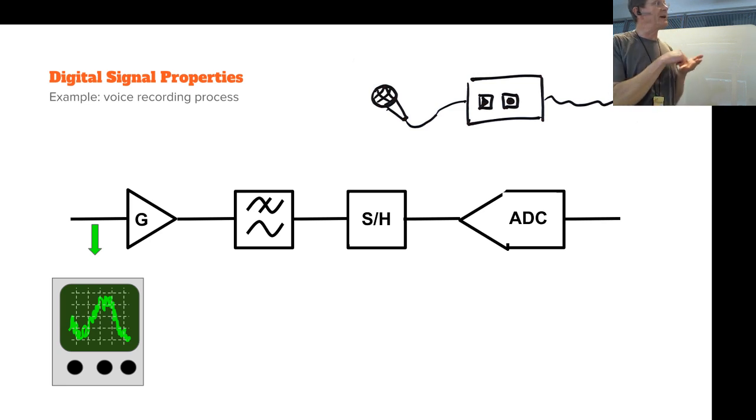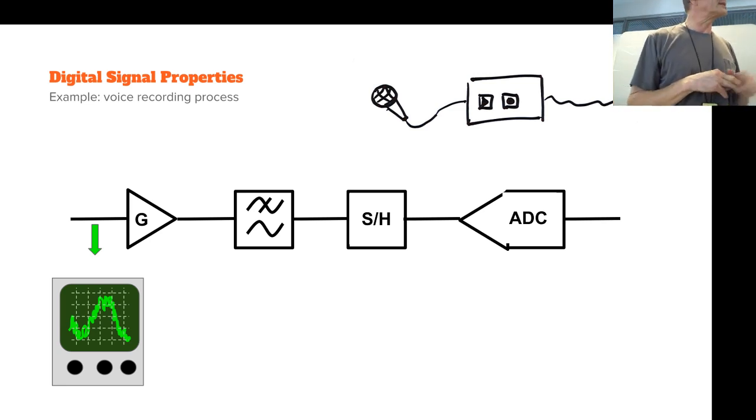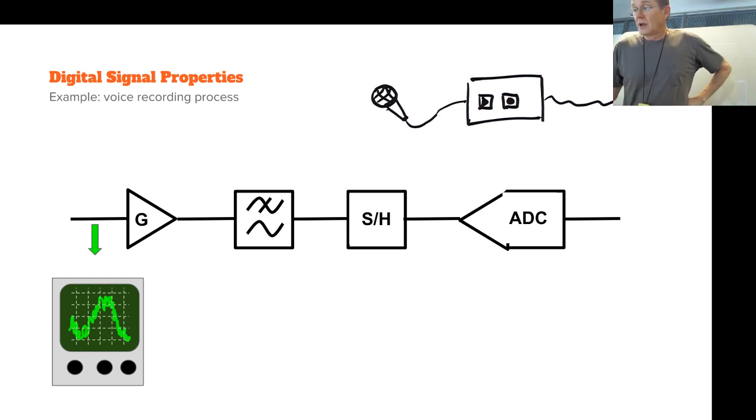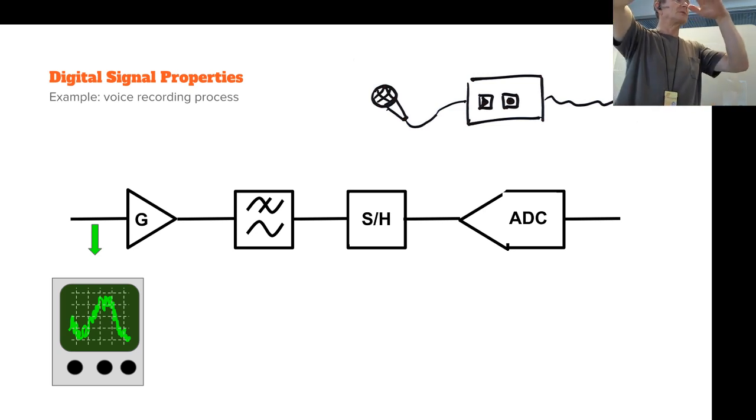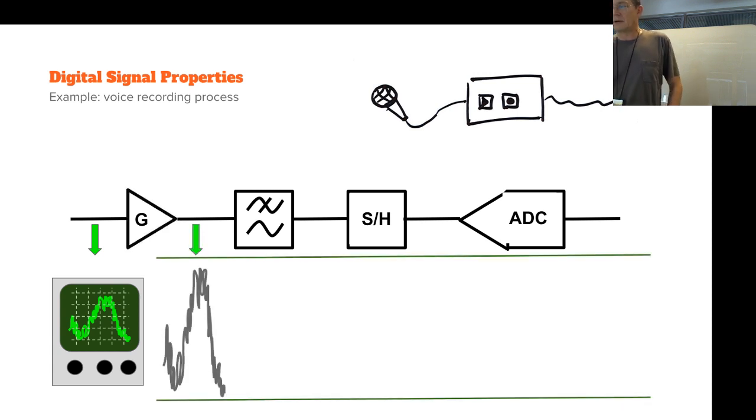So first you have a very small signal on your oscilloscope screen, say few millivolts, maybe max 100 millivolts. But then the A to D converter has usually few volt region that it does the conversion. So what you want to do is to fill that few volts as well as possible. So try to keep those in bound, of course, plus and minus bound, but you need to then do some amplification for the signal. And after that, it's within the bounds of the A to D conversion.